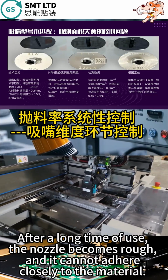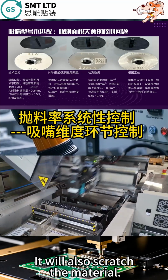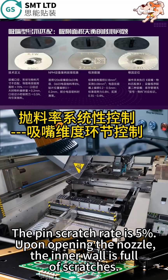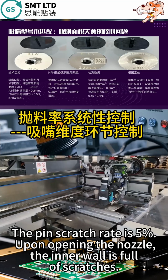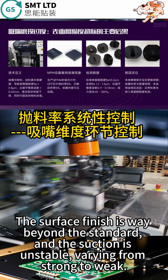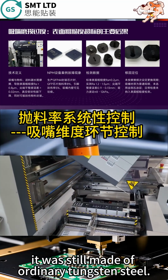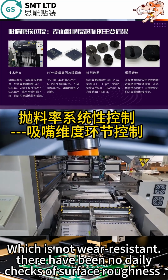After a long time of use, the nozzle becomes rough, and it cannot adhere closely to the material. It will also scratch the material. The yield of packaging QFP chips is 8%. The pin scratch rate is 5%. Upon opening the nozzle, the inner wall is full of scratches. The surface finish is way beyond the standard, and the suction is unstable, varying from strong to weak. This is because the nozzle was not changed according to its frequency of use. It was still made of ordinary tungsten steel, which is not wear resistant. There have been no daily checks of surface roughness.